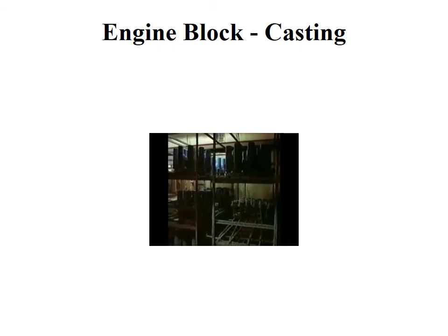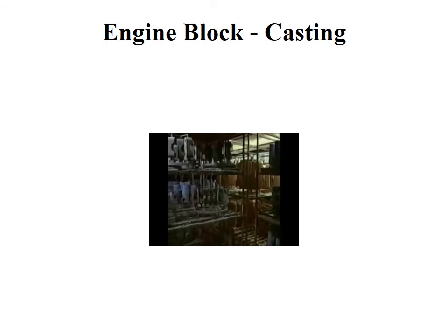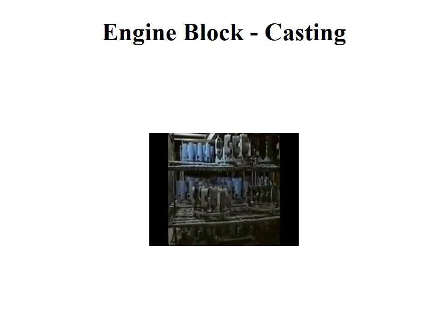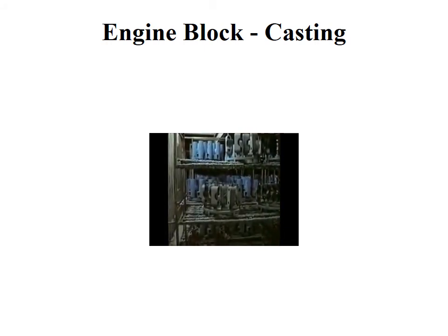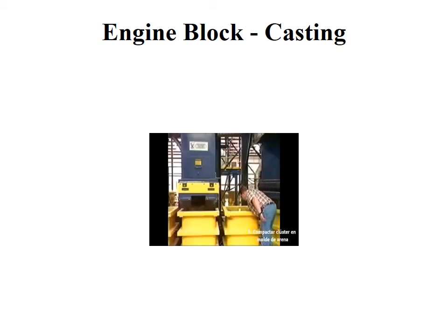The wet, coated foam cluster is then placed in a drying oven to remove the water. Ideal process control and throughput are achieved with dehumidification and internal humidity control. The coated dried cluster is placed in a special steel flask, either manually or automatically. Dry sand with no additives is then rained around the cluster and vibration is applied to the flask.